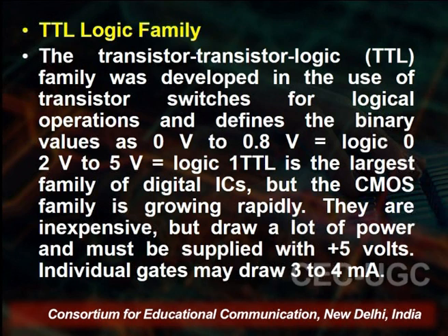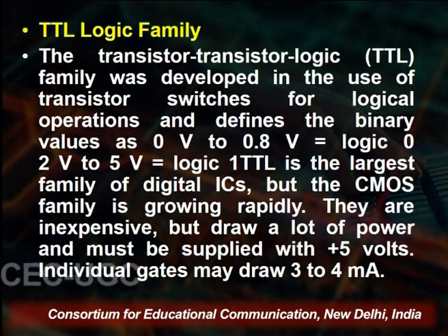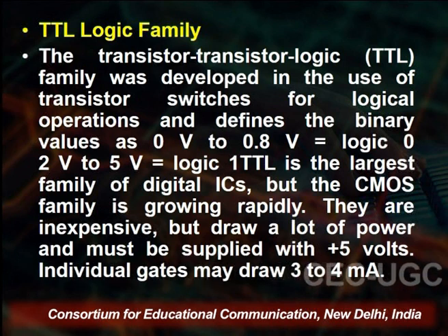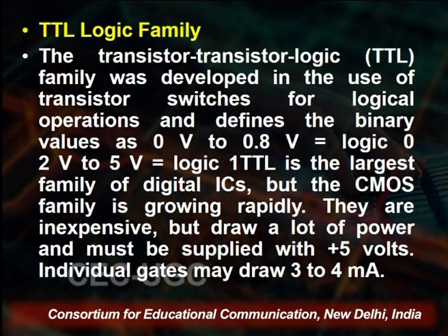So what is the TTL and how is it used? The transistor logic TTL family was developed using transistor switches for logical operations, and it defines the binary values: 0 volt to 0.8 volt is logic 0, and 2 volt to 5 volt is logic 1. TTL is the largest family of digital ICs. But the CMOS family is growing rapidly nowadays, and it is inexpensive, but draws a lot of power and must be supplied with plus 5 volt.